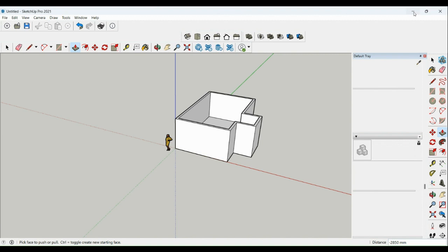It's actually okay because SketchUp is trying to minimize the size of the file that you will be working on. That's why it doesn't want two files open at the same time. So I will open the one we did last time. This, right? Now I have two sessions. So now let's try if we can copy from one file going to the other. Click this. I will copy this. This is already a component, right? So it's good.